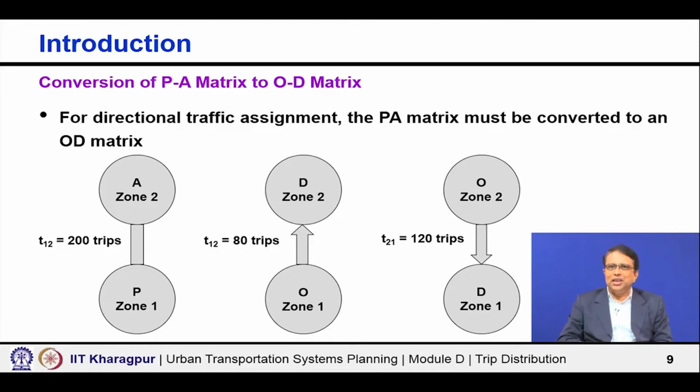Why? I explained it earlier that we want to know in the peak direction of travel how many people are traveling. Maybe accordingly we shall see how many buses are required, or in the peak direction how many vehicles are traveling, and then we would like to see where the bottleneck is, or where the road capacity is becoming inadequate, or where the capacity augmentation of the road is really essential. There could be many applications, but we need to know the directional travel, that is very important.